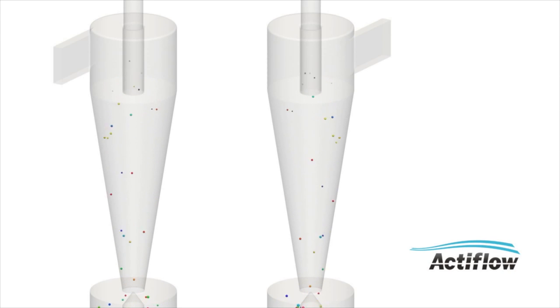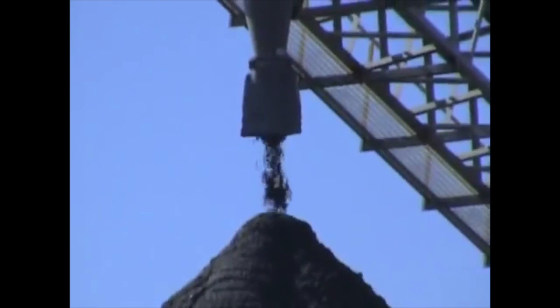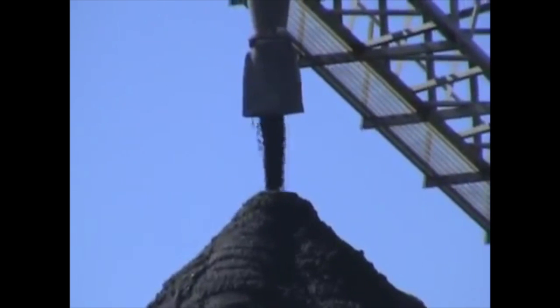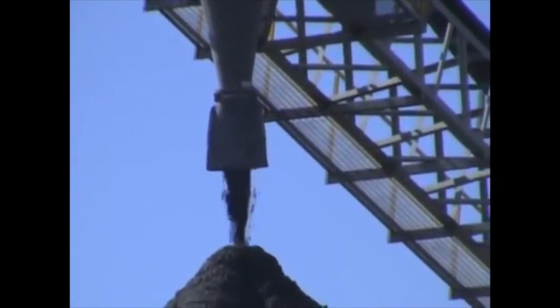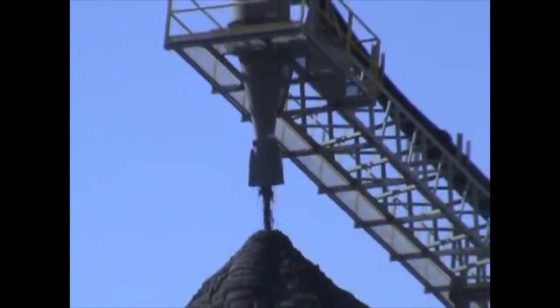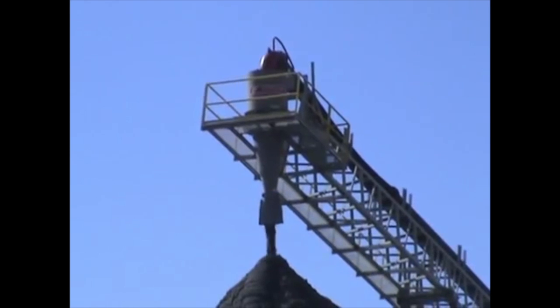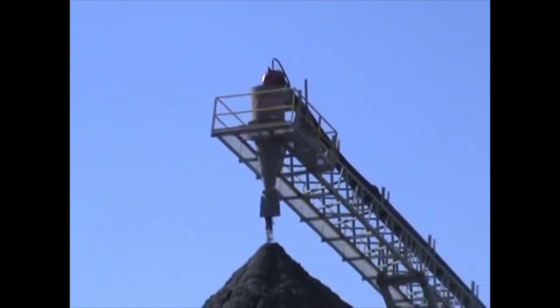Cyclones are used widely across a variety of industries, and they are used both wet and dry. This is a hydrocyclone applied in a large-scale industrial setting. It receives a slurry of mostly water and coal, and it continuously separates the coal for use elsewhere. Cyclones such as this have low maintenance costs due to simple designs and having no moving parts. They are also able to process high volumes of material continuously.